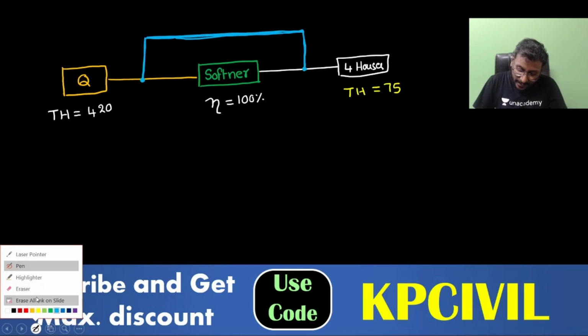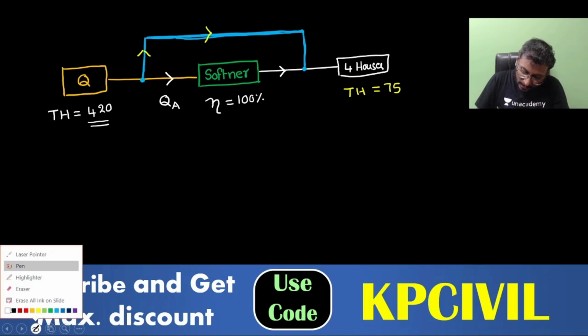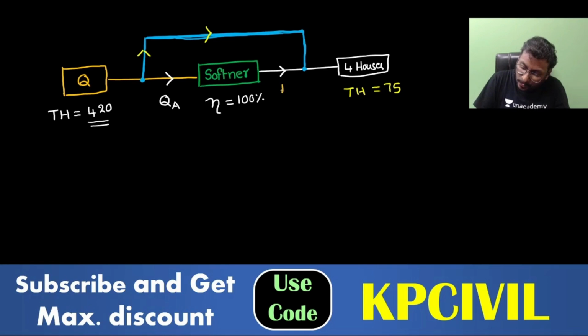I will divide this discharge into 2 components. First component A, QA, which participated in softening, 100% of its hardness is removed and achieved total hardness THA of 0. 100% removal of hardness is achieved.